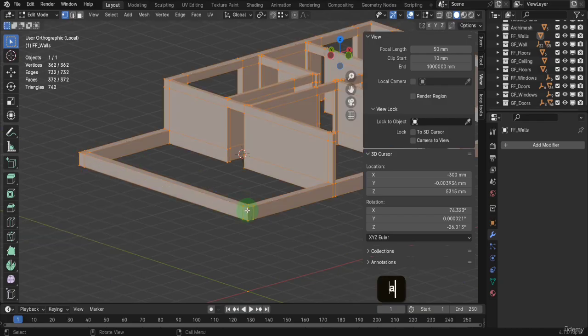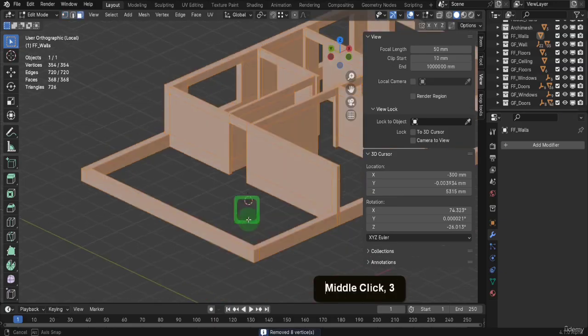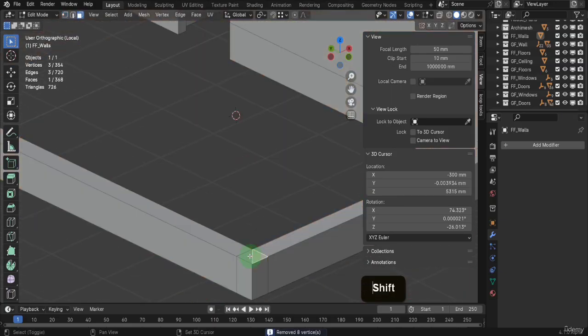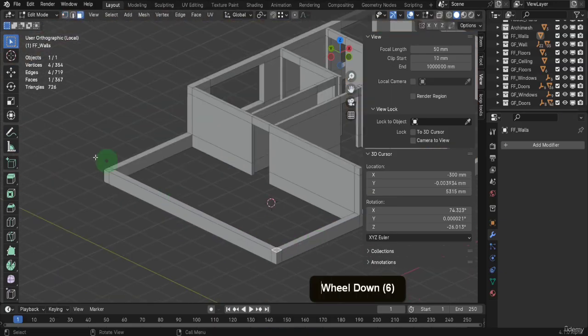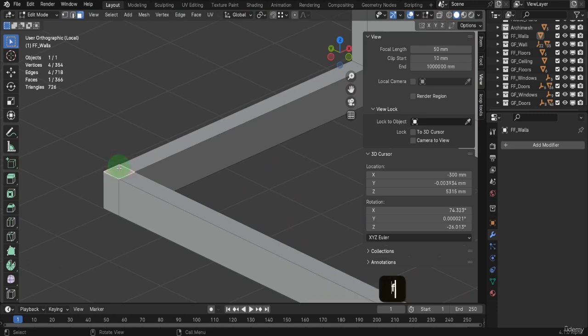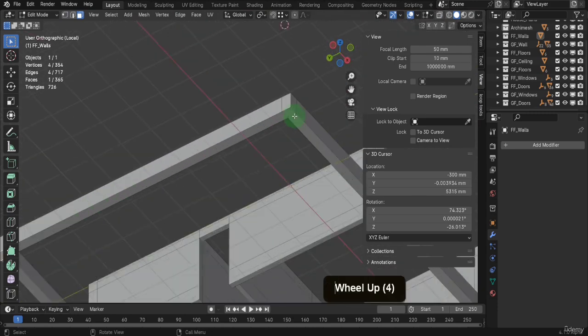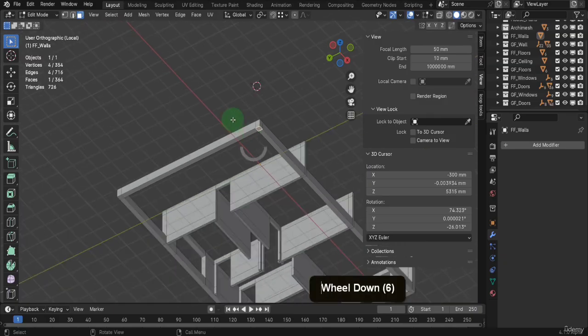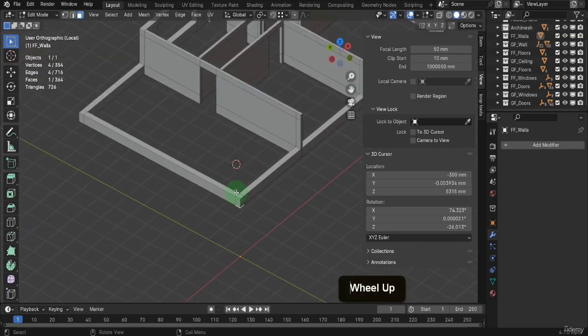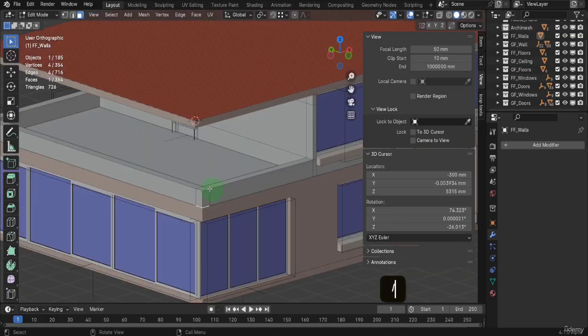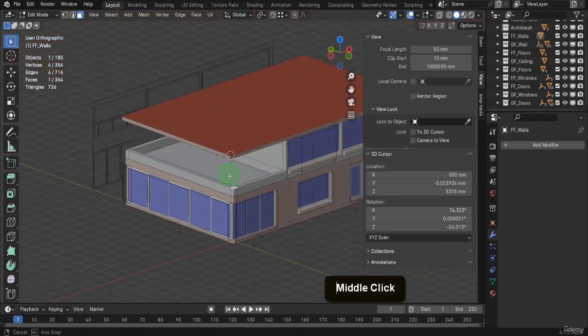Select it all now. Press M and we can merge by distance. Select the top 2 faces. Press F and create one face. Repeat that on the far side. Also, underneath and match the tops. We can return to Global. Now we are ready to extrude.